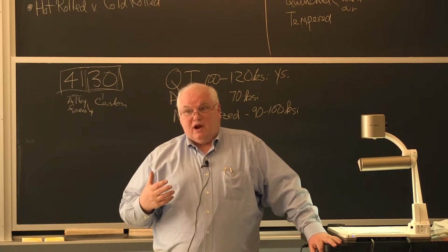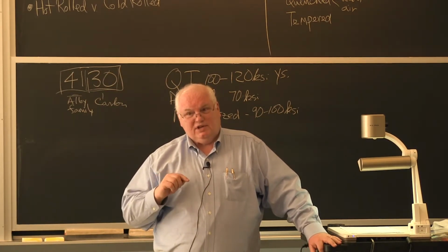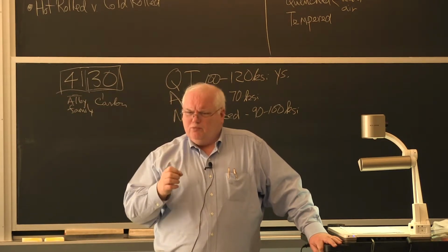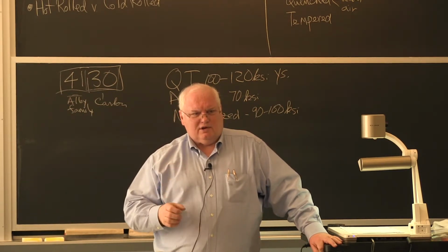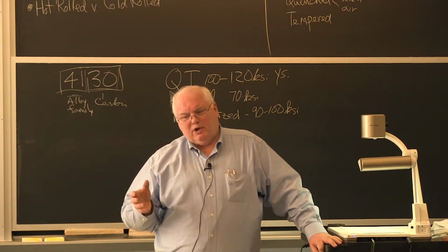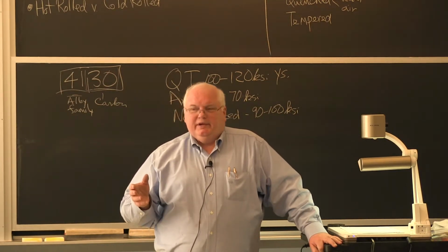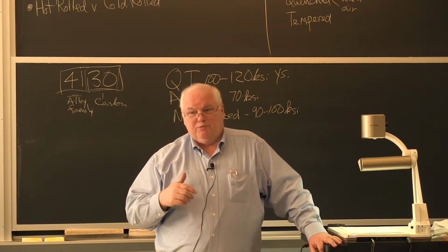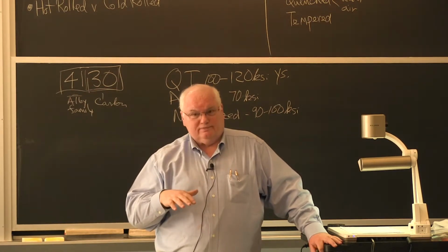And it was a ductile fracture, except it had some fatigue early on, and it was nice chrome plated, of course, to make it look nice. And the problem was the final fracture was ductile. It wasn't brittle, but the beginning fracture was brittle.